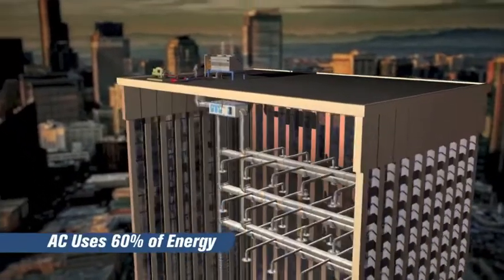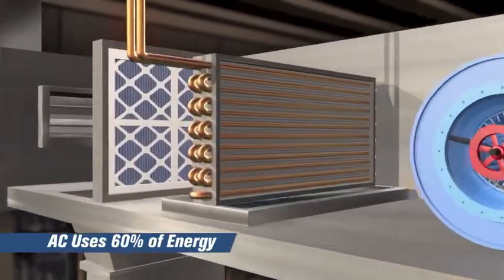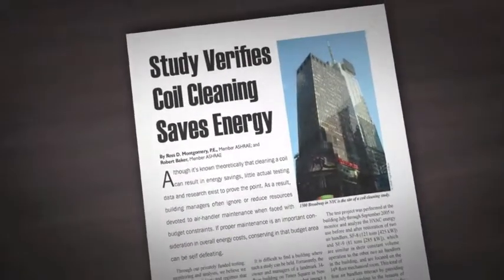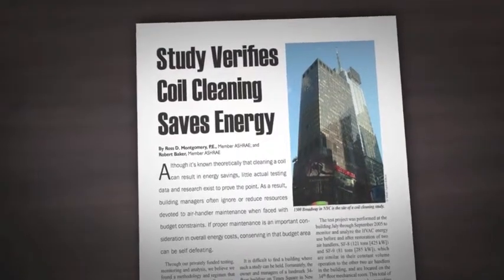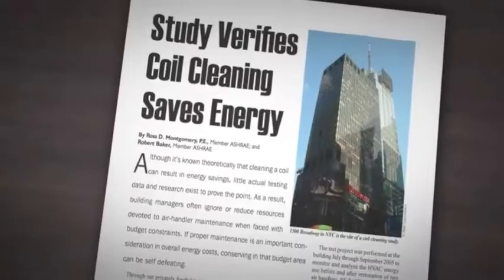In a typical office building, the AC system uses 60% of the building's energy, and of this, the chiller and pumps consume 70%. The 2006 ASHRAE published study estimated savings of 15 to 30% from a clean coil.